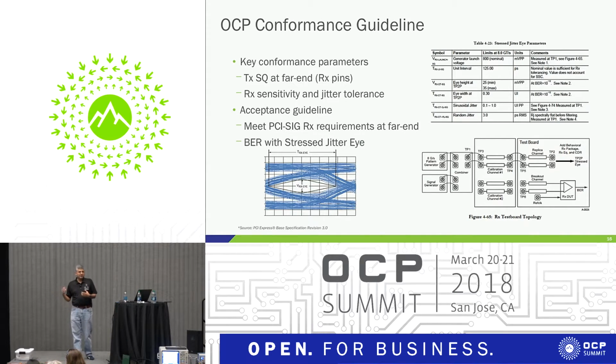So we are leveraging a lot from the PCI CEM to help us define how we test in the OCP environment. In the first phase, we are targeting mostly transmit signal quality and receiver jitter tolerance.